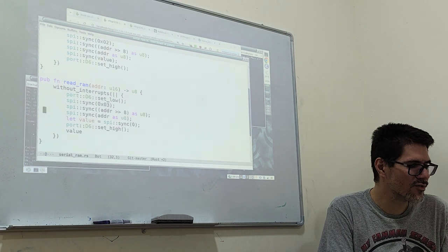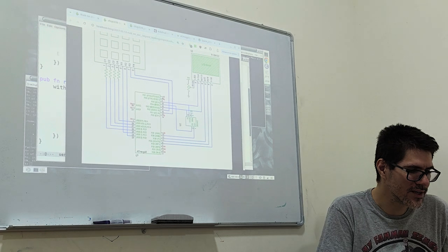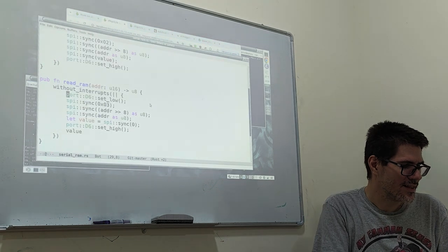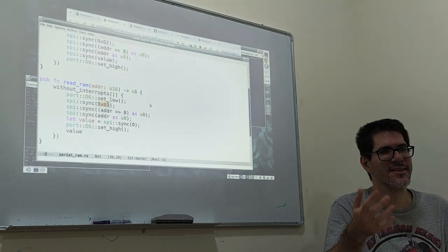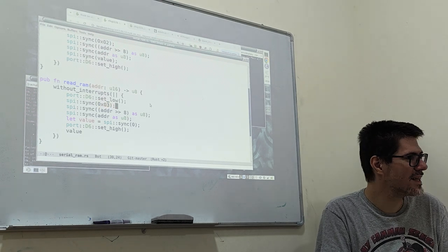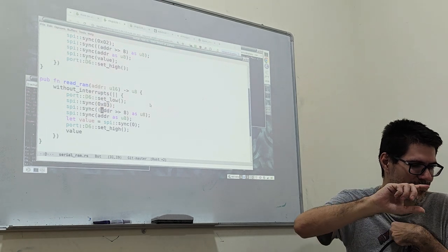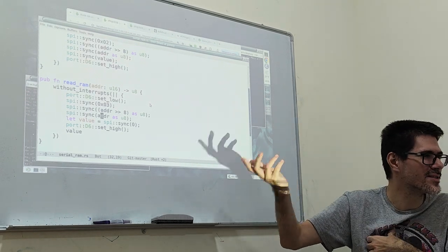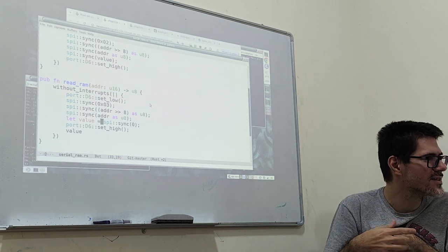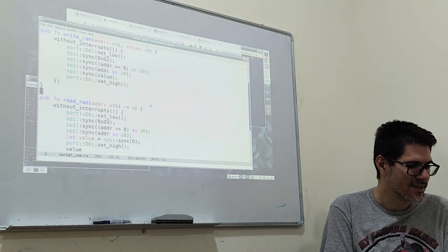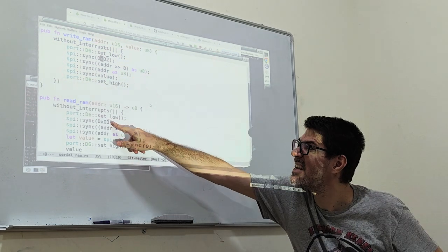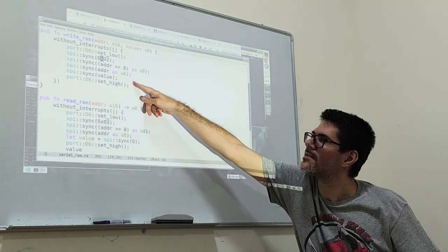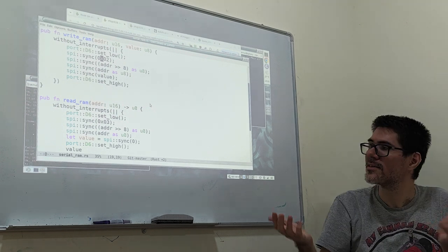connected to SPI. If you want to read from it, you pull low a different port, the one that is connected to this guy instead of that guy. So you pull this low, and then you send out the magic number that, again, you need to look up in the datasheet, that you want to read. Then you send out the high byte of the address, and then the low byte, because this is larger than 256 bytes, so you need more than 1 byte to address, and then you get back the result by the same SPI, and that's it. And you need to write. The difference is basically that the command instead of 3 is 2, and 2 means write, 3 means read. Exact same thing, and of course, if you send 2, then you need to send the value that you're writing, but it's the exact same story.